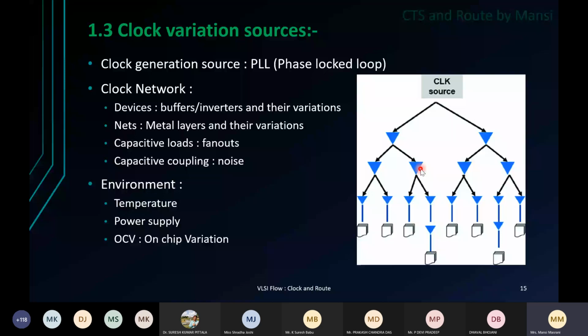Now the capacitive coupling, which we talked about, the noise. Any two nets which are going side by side will have some capacitive charge effect between them, which will result in noise, whether it's a glitch or a delay.